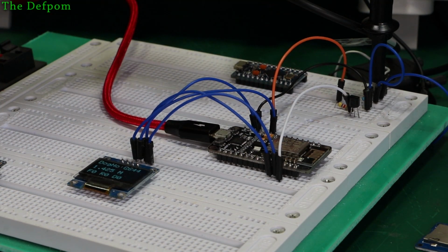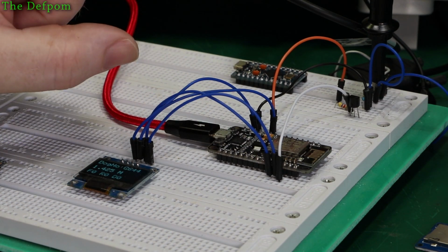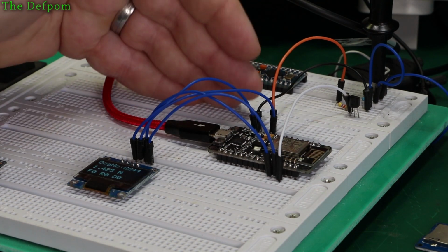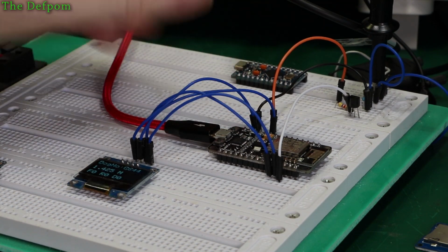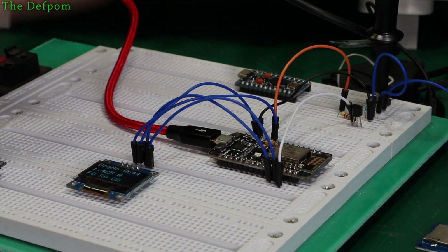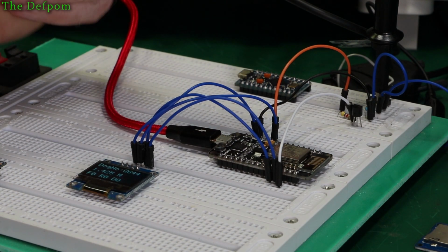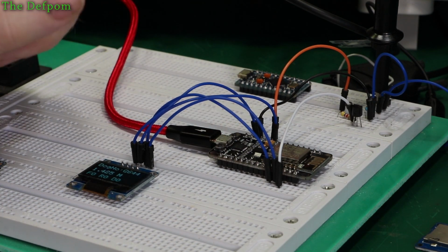What I'm doing is because the protocols that come out of this device are not true UART, it's using an idle low state instead of an idle high state. On a scope it doesn't matter, because you can just change the state and it will decode it. It's absolutely fine, so you'll be able to see that on a scope shortly. For this device here, or the Arduino, they require an idle high state in order to decode using the standard protocols, without having to rewrite stuff.